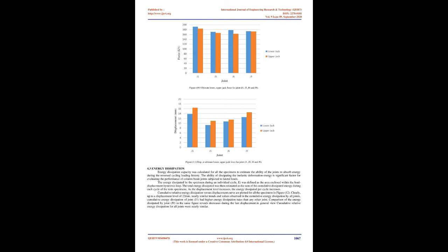In the specimen J9, rectangular column with same width of beam, a similar trend was observed in both directions, but the load drop started at an average of 12.54 mm. In the specimen J5, rectangular column, a similar trend was observed in both directions, but the load drop in positive direction first at 9.26 mm then in negative direction at 11.01 mm.